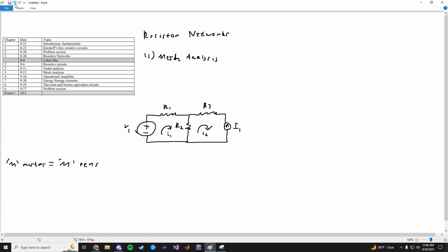So that being said, compared to nodal analysis, how you solve these problems, one technique might be easier over the other. Like for example, in this example circuit, you would want to use nodal analysis because you only have one unknown node. But if you use mesh analysis, you have 2 unknown meshes. That would lead you to have 2 equations. So then you'll have a system of equations rather than one equation to deal with. But for the sake of understanding mesh analysis, we'll go ahead and mesh this up.